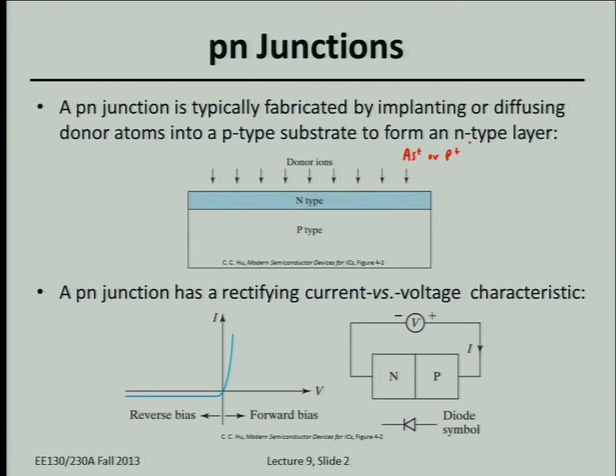Once they hit the surface of the wafer, there's an electron gun that then attracts, because the wafer will get positively charged, right? So this electron gun will just provide electrons to the surface to neutralize it. So as implanted, the surface of the wafer is actually charge neutral. But we have to ionize those atoms in order to give them kinetic energy to embed themselves into the surface of the wafer. So in principle, all you need to know is that we implant arsenic and phosphorus atoms. There's no net charge introduced by the implantation process.